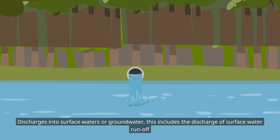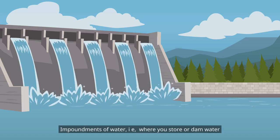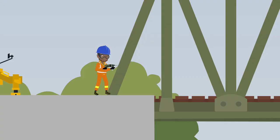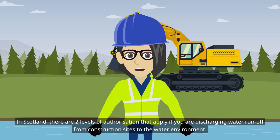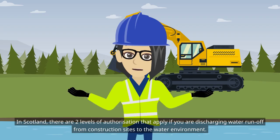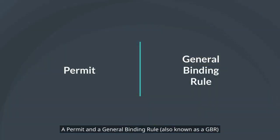This includes the discharge of surface water runoff, abstraction of water, impoundments of water, i.e., where you store or dam water, and engineering or building works in or near to inland watercourses. In Scotland, there are two levels of authorisation that apply if you are discharging water runoff from construction sites to the water environment: a permit and a general binding rule, also known as a GBR.